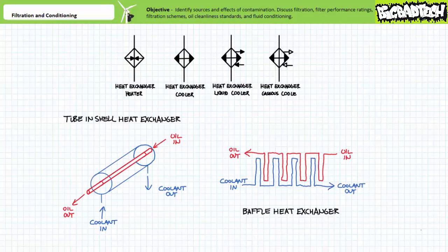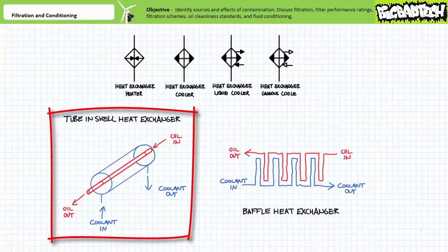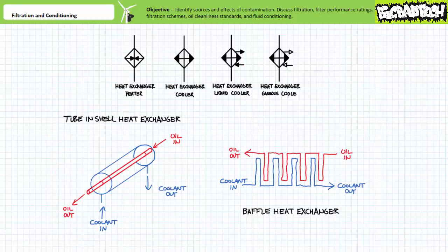Coolers employing heat transfer fluids must circulate the oil to be cooled and the heat transfer fluid in opposite directions. A tube and shell heat exchanger employing a liquid heat transfer fluid is essentially a tube containing the oil to be cooled, jacketed by a shell containing the heat transfer liquid. Warm heat transfer liquid leaving the heat exchanger is still cooler than hot oil entering, as is warm oil leaving the heat exchanger hotter than the cold heat transfer liquid entering. This counterflow arrangement ensures heat transfer occurs the length of the heat exchanger.